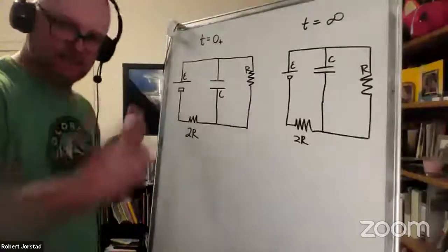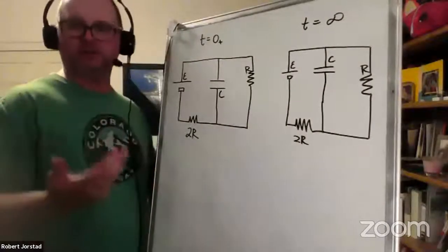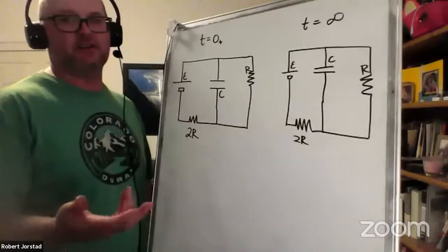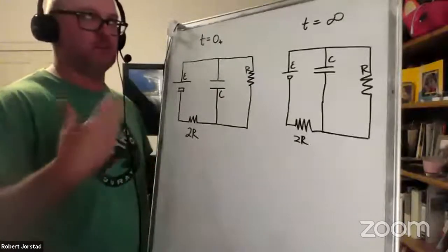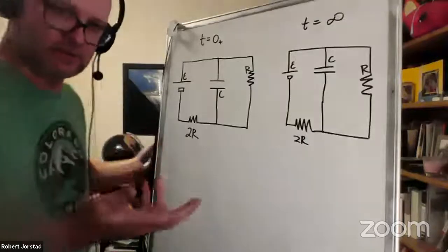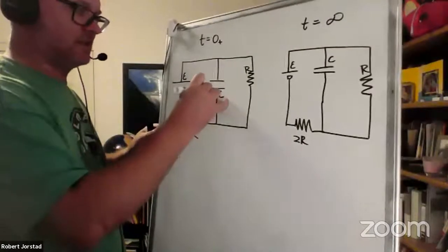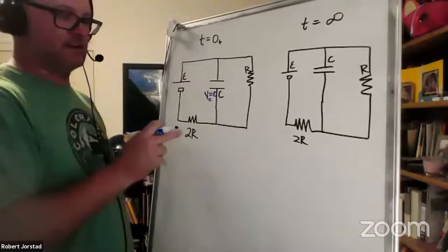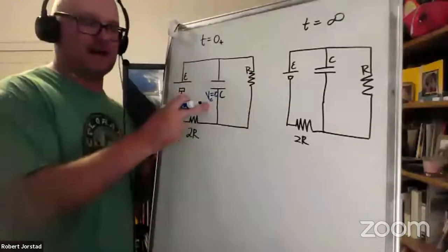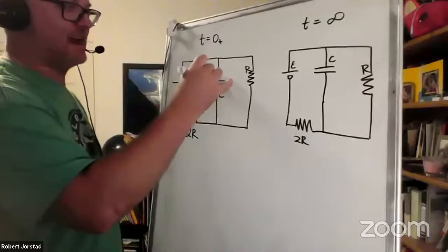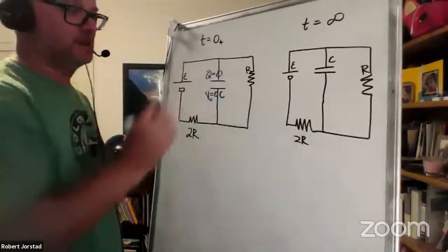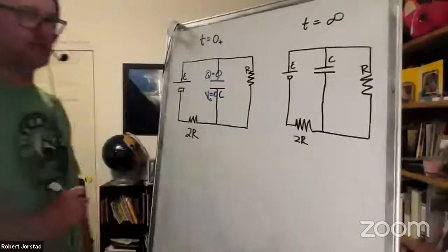Right. And then just to try and keep with the wording, I would actually focus on the voltage first, because the mnemonic device is capacitors preserve voltage. So he's absolutely right. The voltage is here. You were both right. That's 0. Because it's been open a long time, I know there's no voltage. From that, I know there's no charge. All right. So now how does that help me?